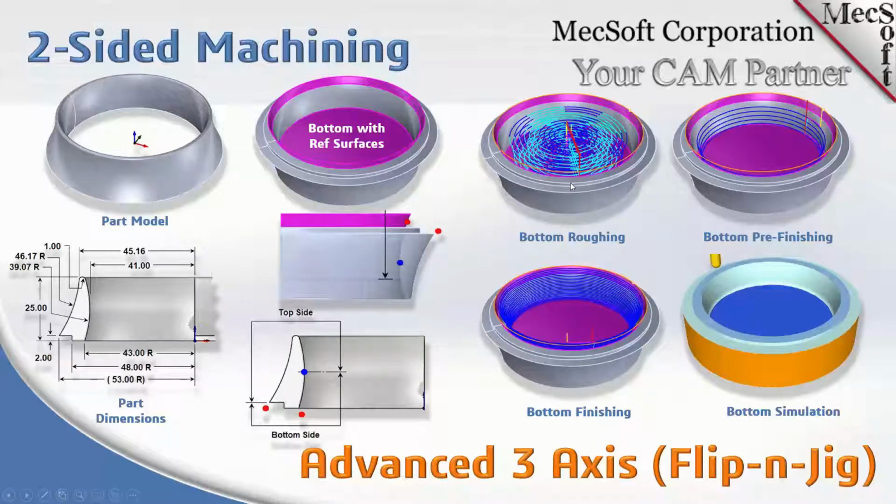So on the third column, we're machining the bottom of this part first. So we're going to be fixing it when we tip it over. So all we need is just a circular round stock, and we're programming the bottom side. So we have the roughing operations in the top view, and then we have a finishing operation in this view here. So if you move over to the final column on the right, on the bottom, you see the cut material simulation of the part.